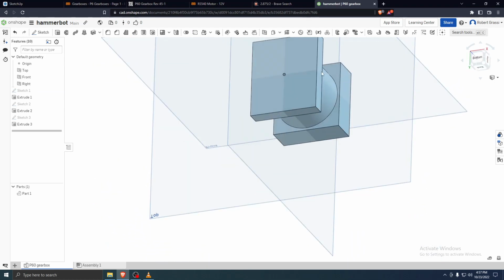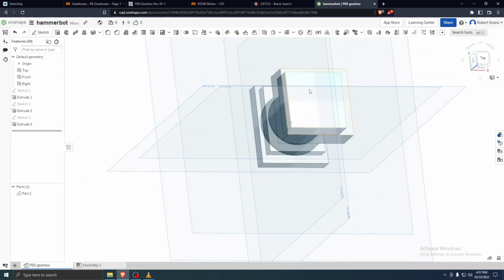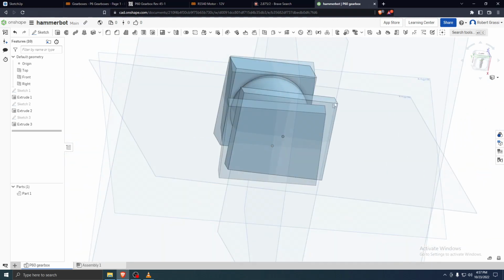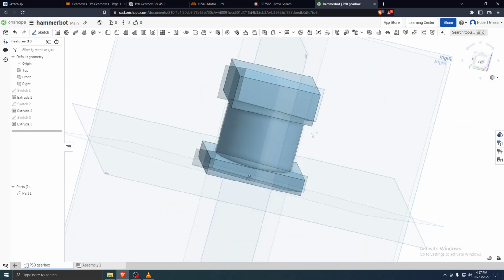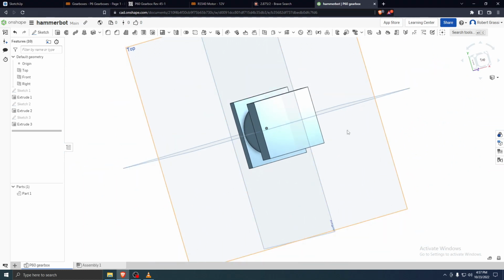So if you want things to update in relation to each other, you have to constrain them relative to one another, which is the basis for what's called parametric modeling. Basically, you have a certain base dimension, and then you can have sketches or features be dependent on those other dimensions, as opposed to having to tell in absolute terms exactly what the distance is.